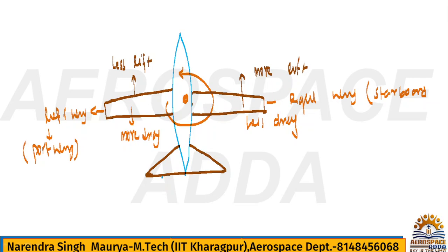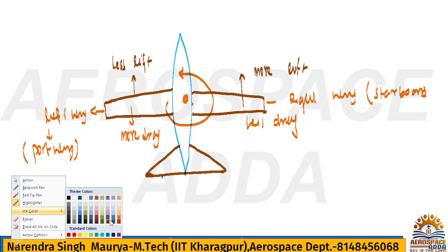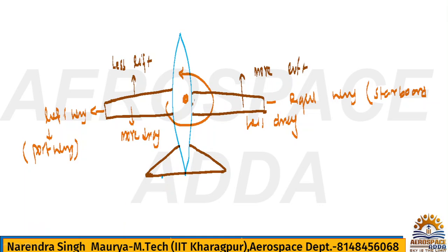So once this airplane is yawing in this direction, if the airplane itself comes back after the disturbance, coming back to its original position, this is the restoring moment basically. If the aircraft is trying to come back to its original position again, so a restoring moment is suppose it is getting, so you have to say it is laterally stable.